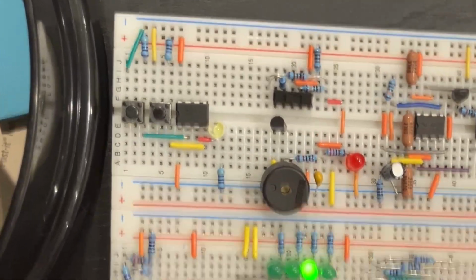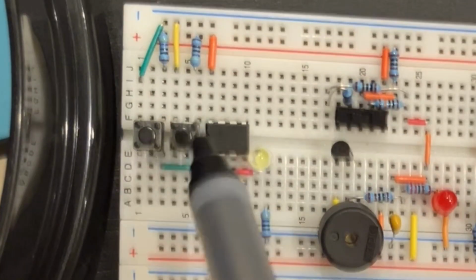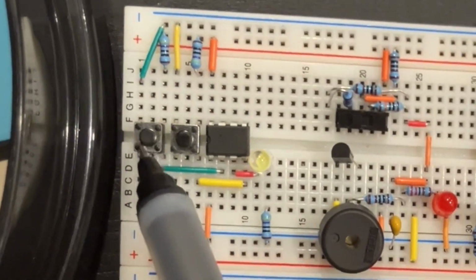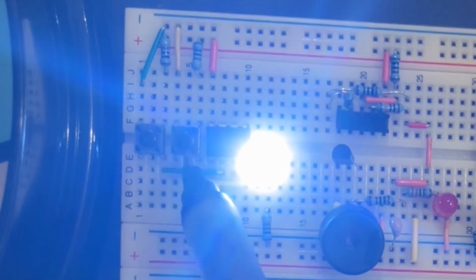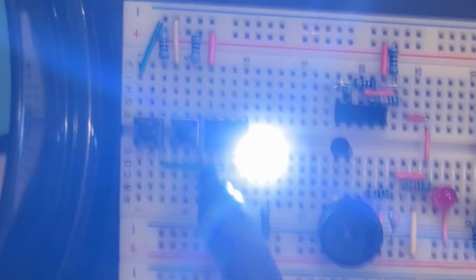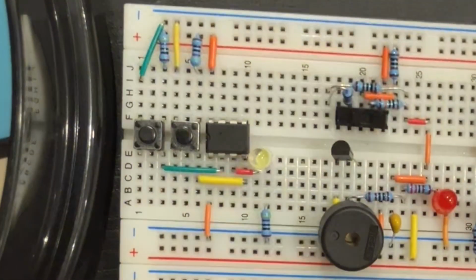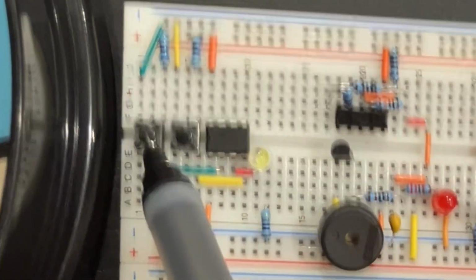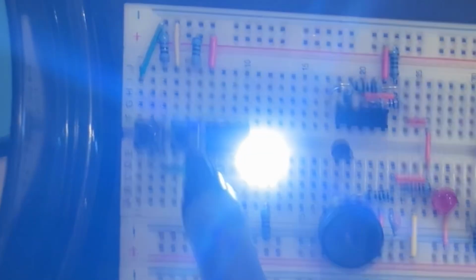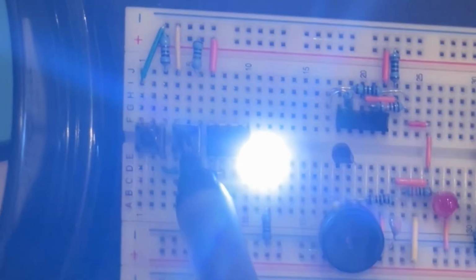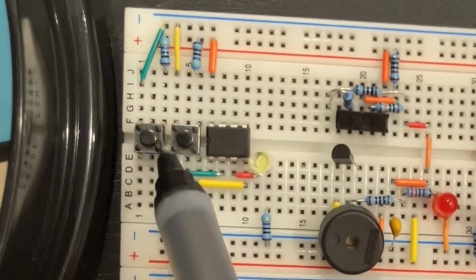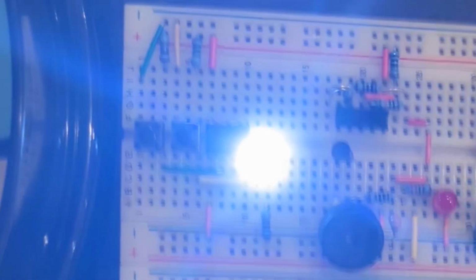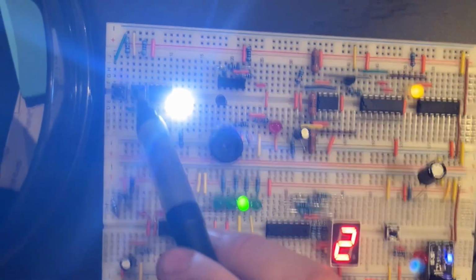This memory latch displays the 555 timer in bistable mode, where it has two stable positions. Essentially, the two PBNOs are connected to the SR latch set and reset inputs. When the left PBNO is pressed, a 1 is outputted and stored, even after the button is no longer being pressed. The right button likewise will output and store a 0. This circuit essentially functions as a 1-bit digital memory, which shows how sequential circuits can store information.